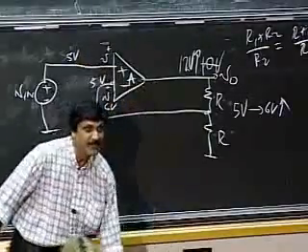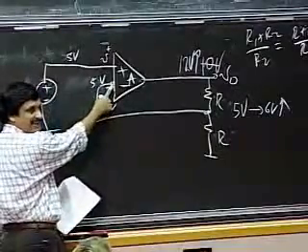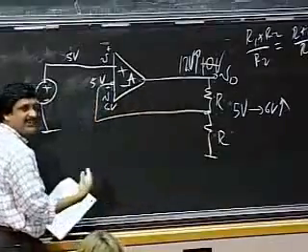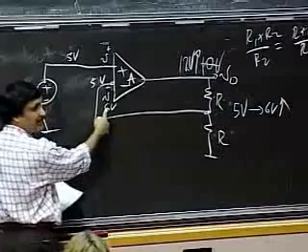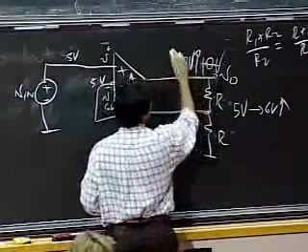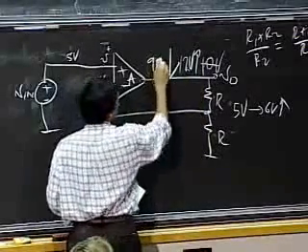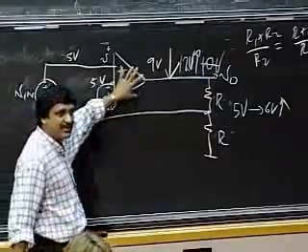Output should go down. Because the voltage at the negative terminal is higher, the output is A times V plus minus V minus. And because this has gone down and this has gone up here, it's going to try to pull the output down. Okay, let's say to 9 volts or something. Okay, ka-chunk. So there's a big battle going on here.